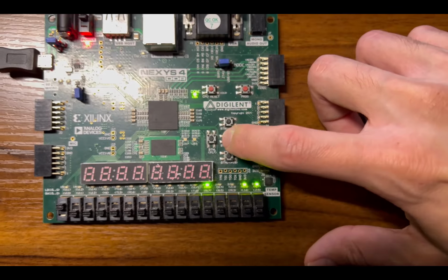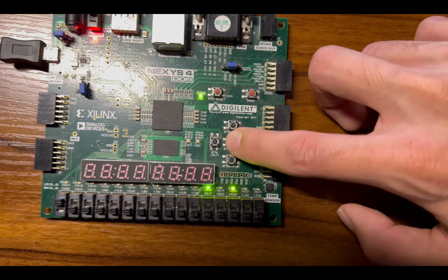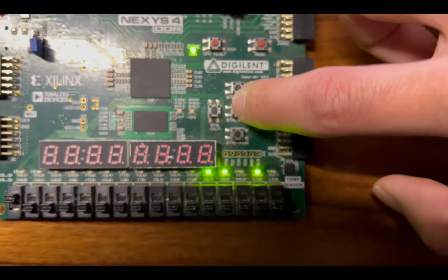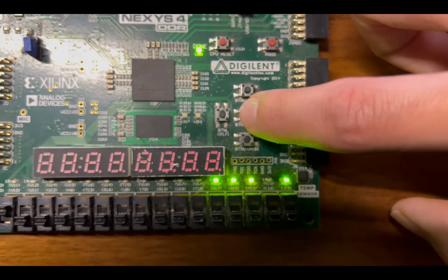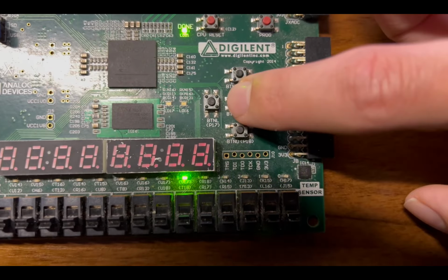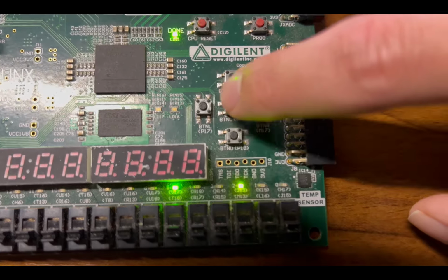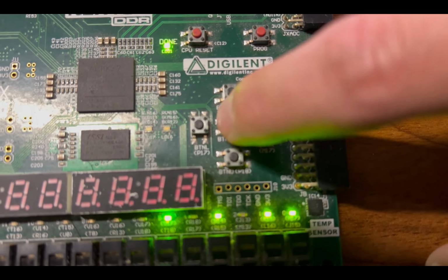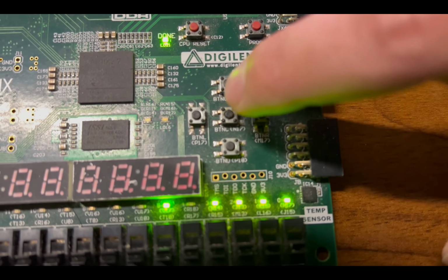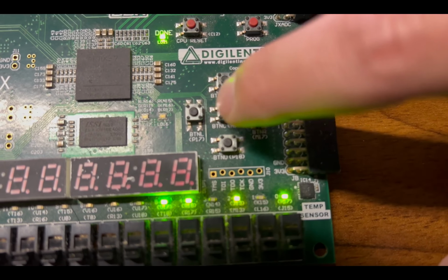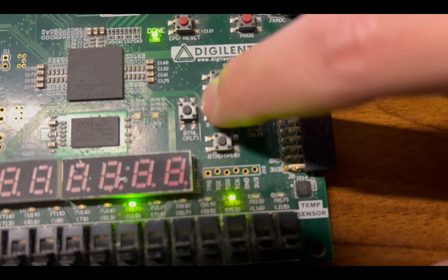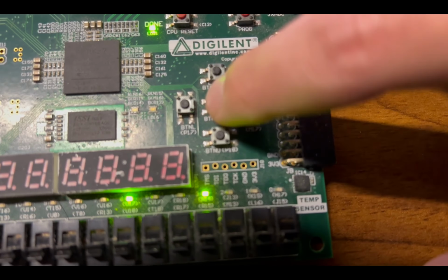This is an extremely important topic because solving this problem right lets you trigger an event from any asynchronous input in a controlled and predictable way. In this video, we will make a debouncer module that lets you safely transfer any asynchronous signal into your system clock domain. The beautiful thing is that this debouncer module only needs to be written once. Once you have it, you can reuse it forever. Just instantiate it whenever you need a clean, clock synchronized input.